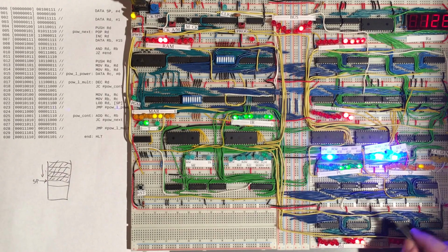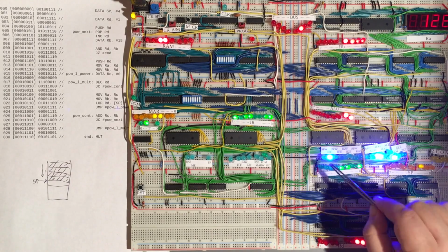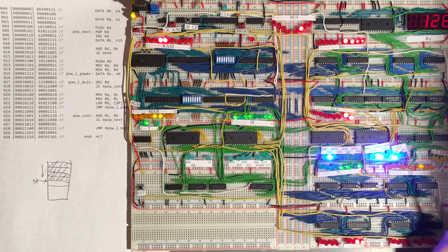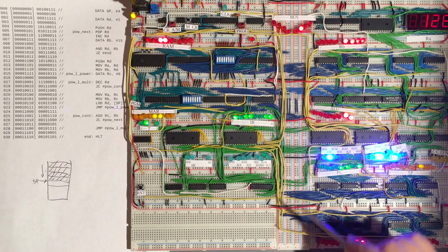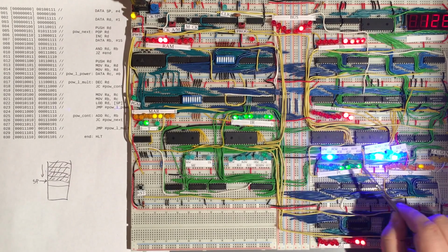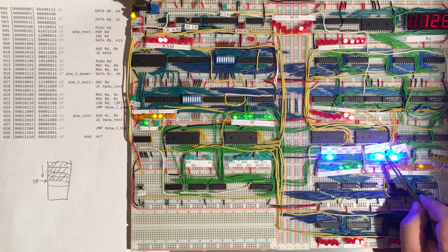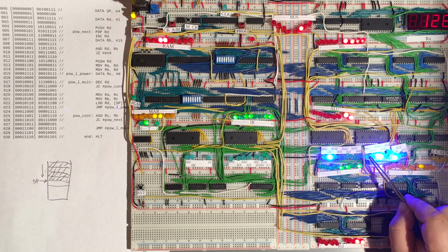So in this case, we're obviously again outputting the stack pointer contents, which are 4, onto the bus, but we're not immediately writing them into the memory address register, because this 4 is not where we want to write the value which we're pushing on the stack. We need to decrease that by 1 first, and so in this first operation, in fact, we'll only be using the ALU. And so as you can see here, the operation code is 0, 1, 0, which corresponds to A minus B. We have not set the carry flag, which for a subtraction means that we do want to borrow.